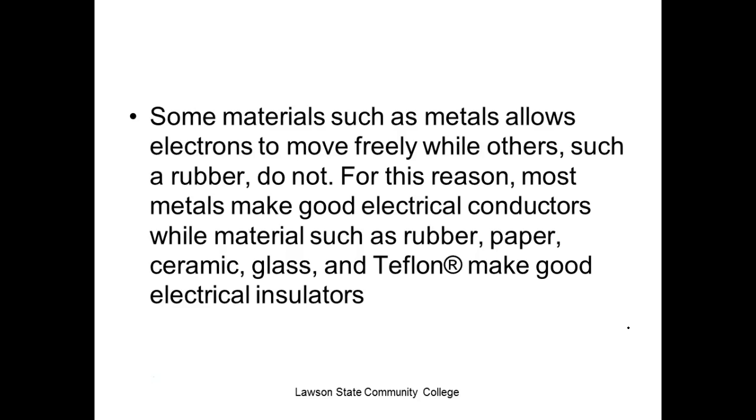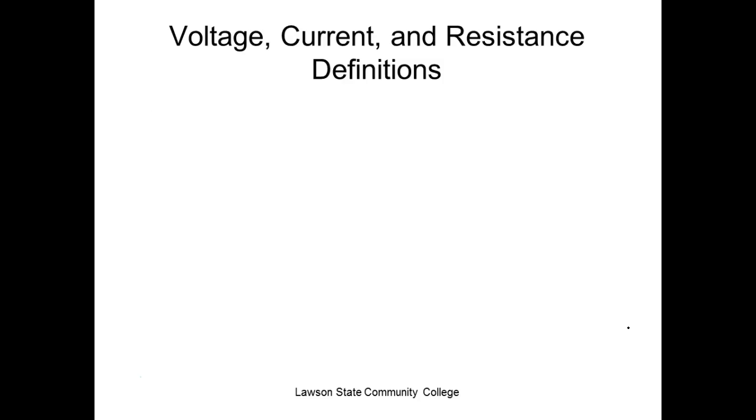The problem is when we put insulation on. So what do we wear in the wintertime to keep warm? We put insulators around a conductor, what's that going to generate? Heat. What happens when we heat a conductor? Its resistance goes up. So this is when we look at the ampacity, the current carrying capabilities of a conductor. NEC has changed the current carrying capabilities depending on what insulator you use. So if you're ever in house wiring, you can't say a 14 gauge wire will handle 30 amps. That's 30 amps if it's uninsulated, right? You understand? So we'll show you all that table too.